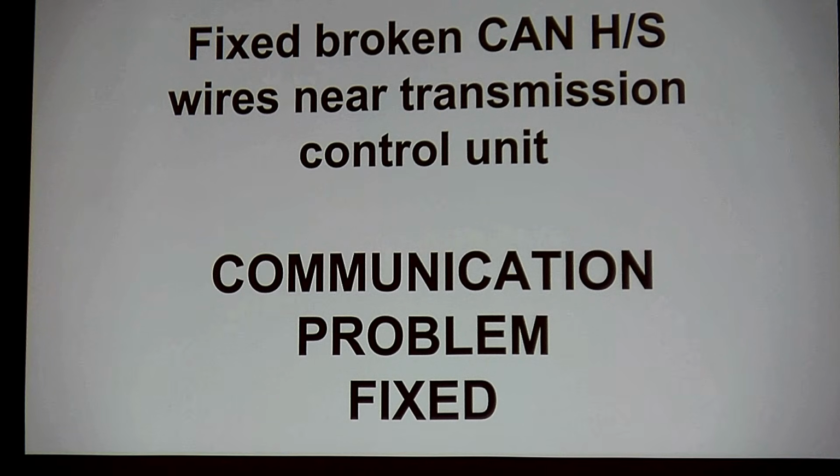So we want to always be looking. Don't cut wiring harnesses open, guys. You'll do way more damage. We only cut wiring harnesses open if somebody put too big a fuse in or something like that, we melted things, or we've got multiple problems. But other than that, we don't cut wiring harnesses open.